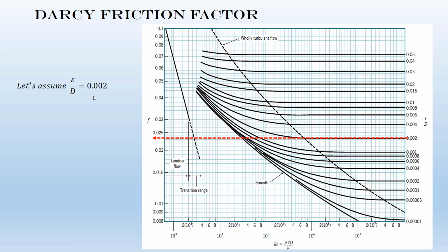If you look at this chart, guys, you can see that the friction factor F for this specific relative roughness, because the Reynolds number is unknown in this type of problem, changes between this value here, which is almost 0.023, and let's say 0.040, for example, if we assume that this is a turbulent flow.